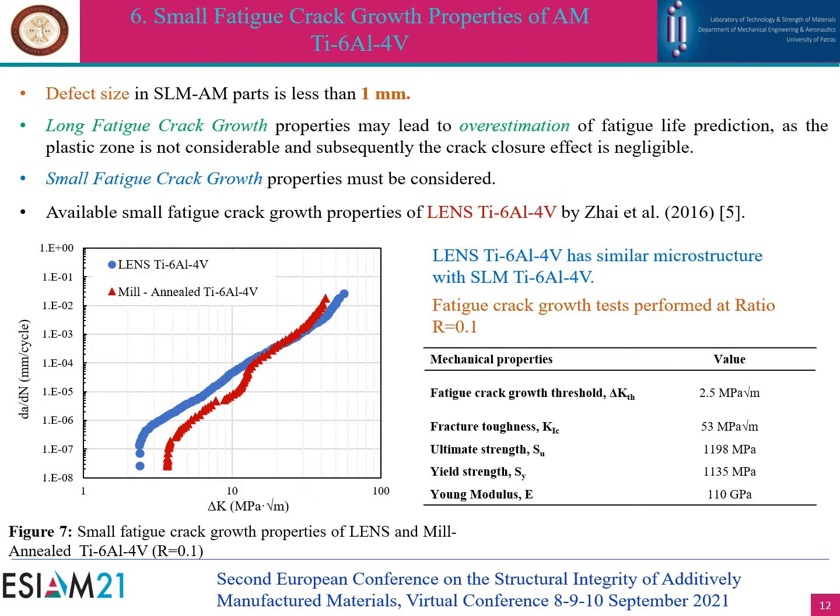Regarding the properties used in the fatigue life estimation model, as the defect size in SLM parts is less than 1 mm, the use of long fatigue crack growth properties may lead to overestimation of fatigue life prediction, as the plastic zone is not considerable and subsequently the crack closure effect is negligible. So, small fatigue crack growth properties must be considered.